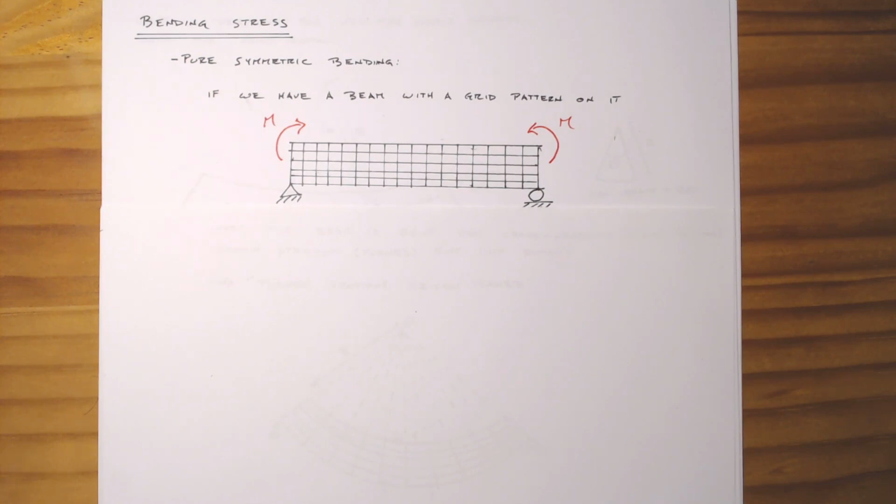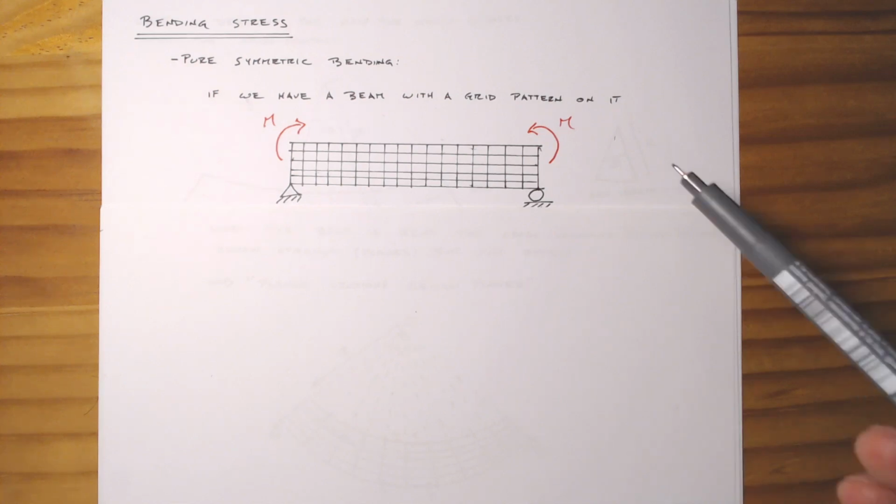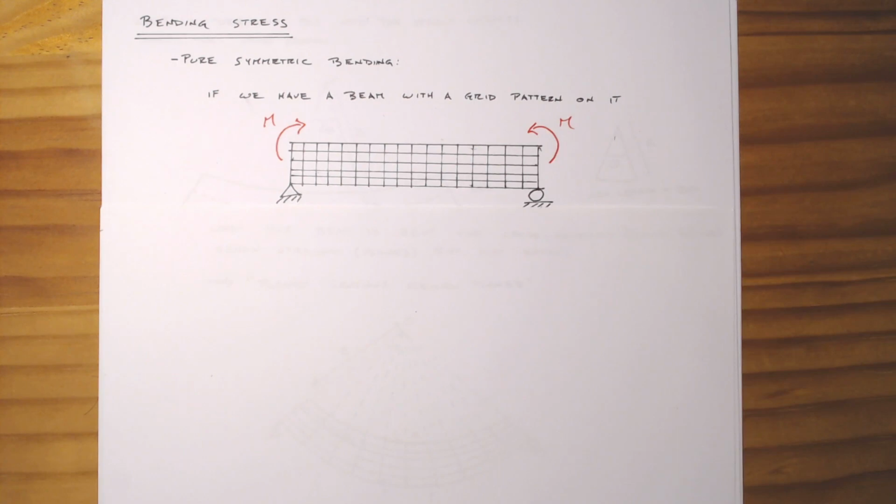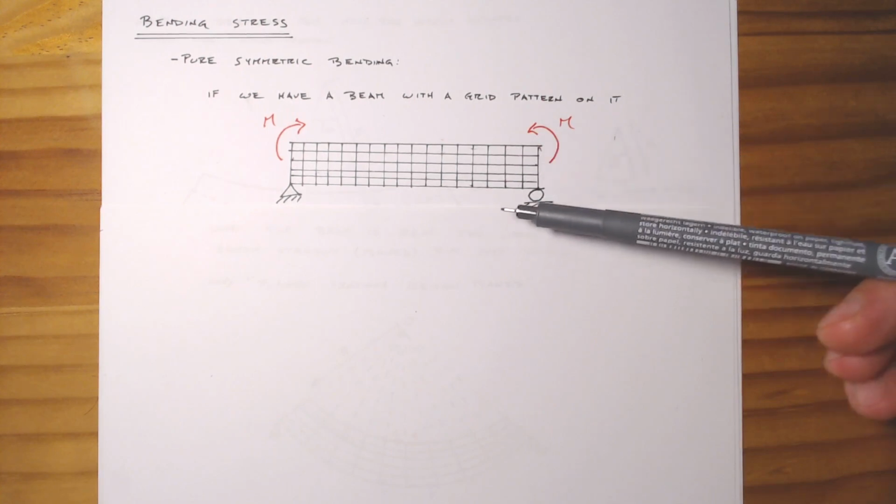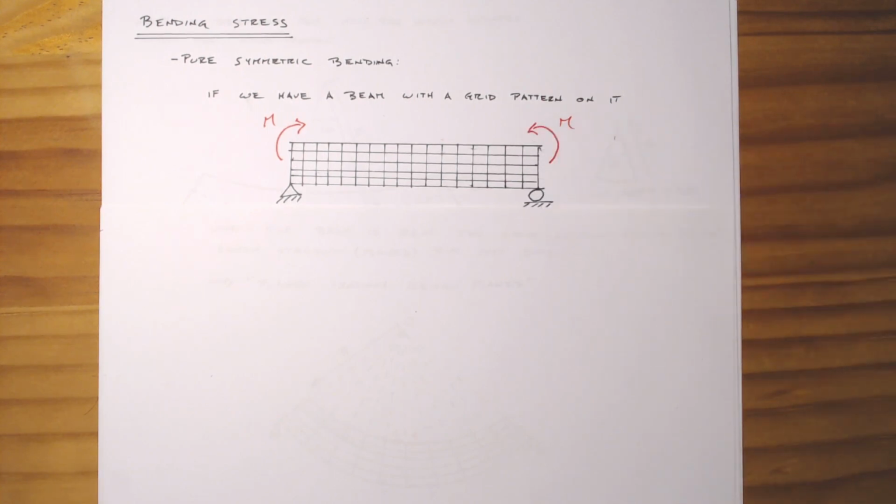And so lots of beams, and all of those beams, if they've got some transverse load, or like what we have here, some pure bending, they will be subjected to some moment, and that moment will give rise to some internal stress from bending. And so our job as a structural engineer is to be able to work out what size beam does this need to be in order to resist the moment and keep the stresses in the beam down low.